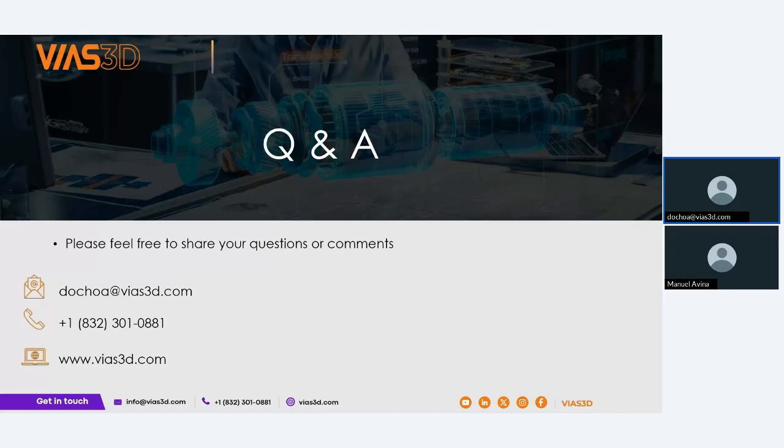The initial mesh that CST creates works for many applications, but if you have a fluid, let's say you have active cooling, you should consider improving the mesh close to where you have fluid surface interaction. Okay, and close to where you have that interaction between surface and background.